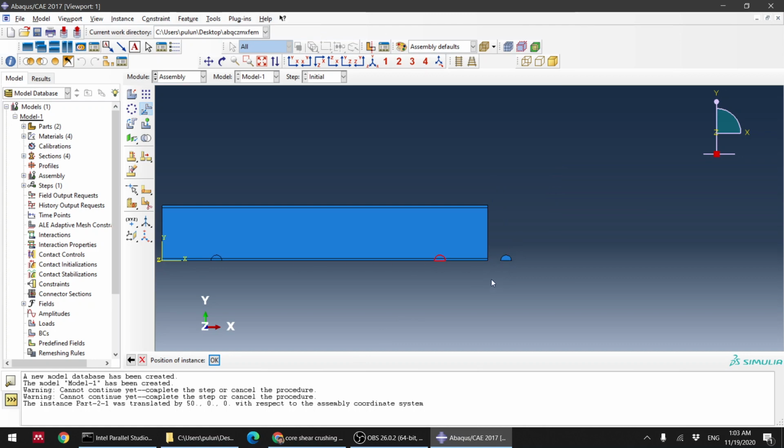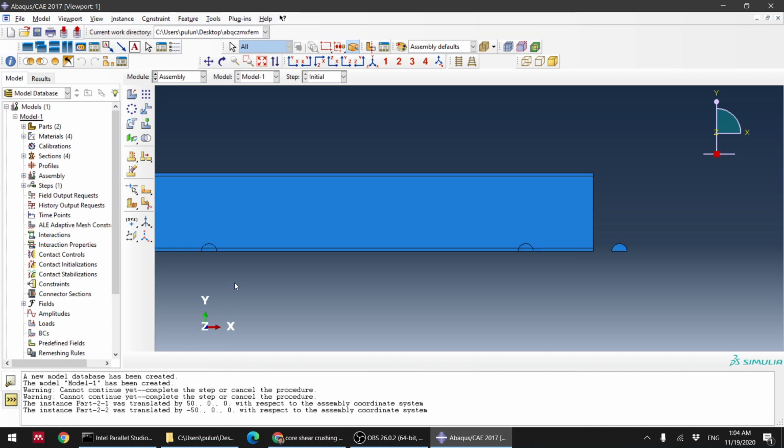The point is that I want to do 3-point bending. It does not necessarily have to be perfectly 3-point bending. I want to introduce non-symmetry here so that my crack will not be exactly in the middle, because that's the point, right? I want the crack to appear somewhere that I cannot predict using the classical method like cohesive elements. That's why I'm using XFEM. So it's okay.